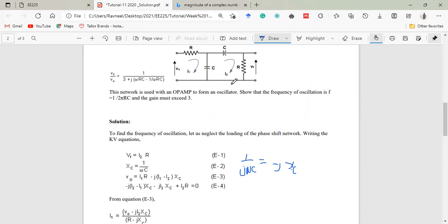In this particular case, let's start from this particular capacitance, right? Remember, if we are considering this particular loop, we consider the current flowing in this loop to be greater than in the other loop. So it will be I2 minus I1, right? I2 minus I1 times the impedance of the capacitance, which is equivalent to minus j Xc. So minus j Xc into I2 minus I1, right?